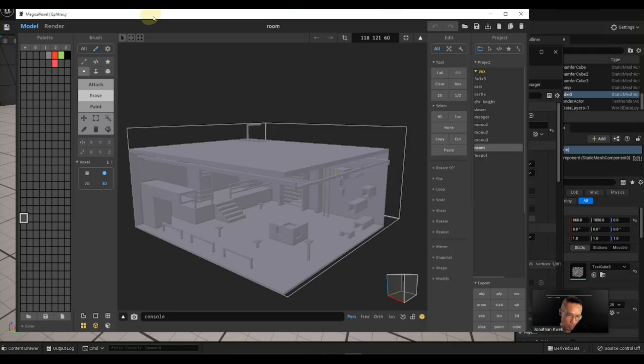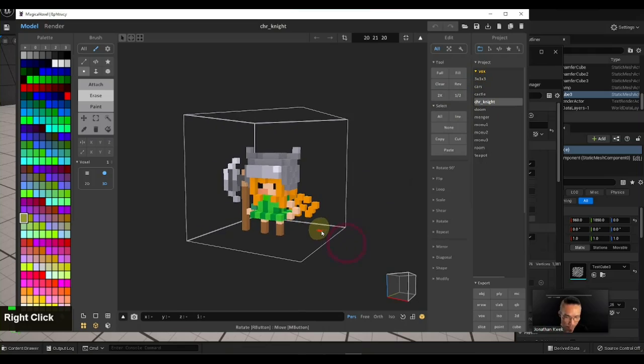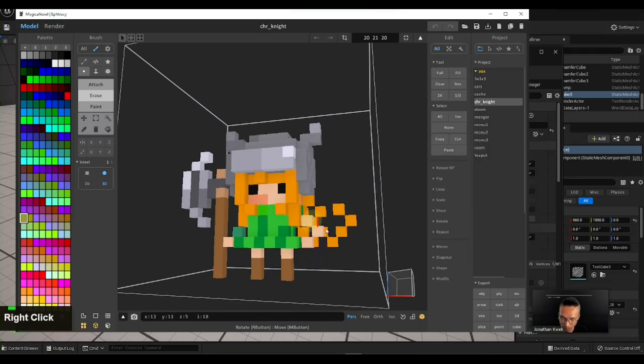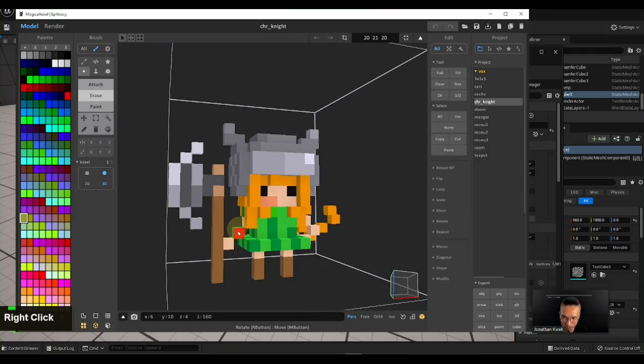If you're using this to generate environment assets, you can basically stop here and then go to the game engine. If you want to use this to generate characters and then use them for animations, there's a little bit of a preparation process where you have to separate some of these body parts away from each other so that you can skin them properly in the 3D software.